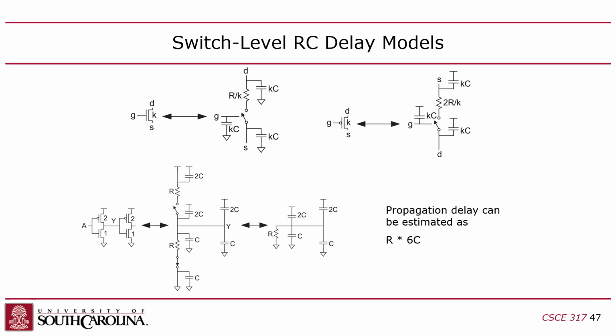So you're fighting against both sides. So it doesn't matter if you've got VDD or ground on the other side. What matters is that you're fighting all four of these capacitors. I'm fighting the source diffusion capacitor of my driving gate, and I'm fighting the gate capacitance of the driven gate, right? So you have to basically just add these up, right?